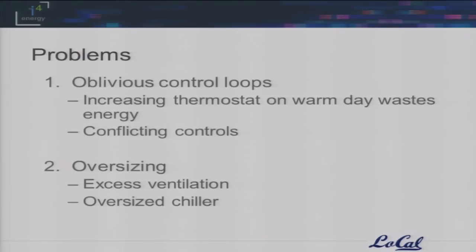And for example, if it seems that demand response ought to be easy, let's just raise the temperature on the thermostats. Well, in this building, we take reasonably comfortable air, cool it down to an incredibly cold temperature, push it real hard throughout the building and reheat it. So raising the temperature only means that we'll reheat it a little bit more. So many things are not at all obvious. And in fact, in many cases, those control loops may be fighting with one another. And yes, indeed, it can be hard to modulate it well because the infrastructure itself is oversized.